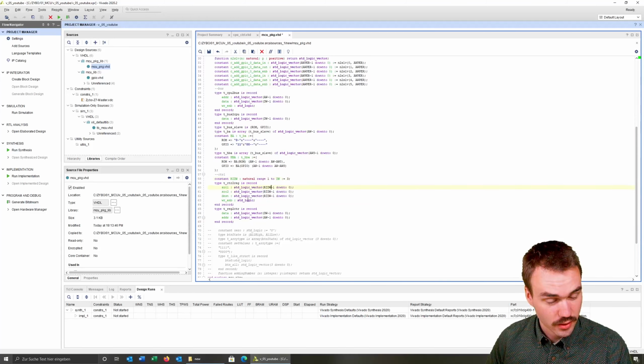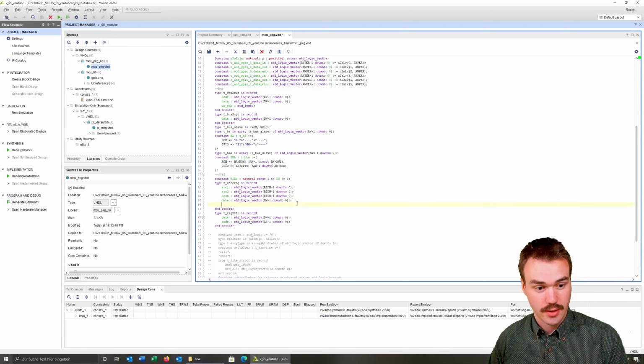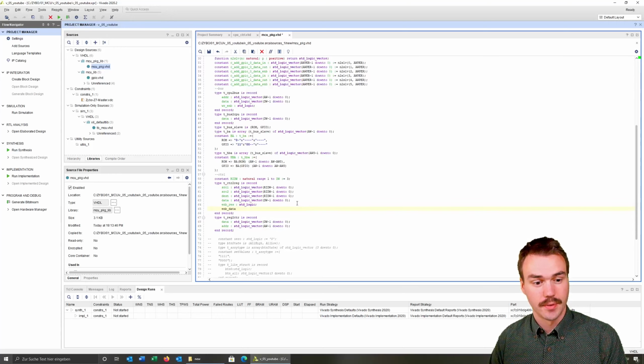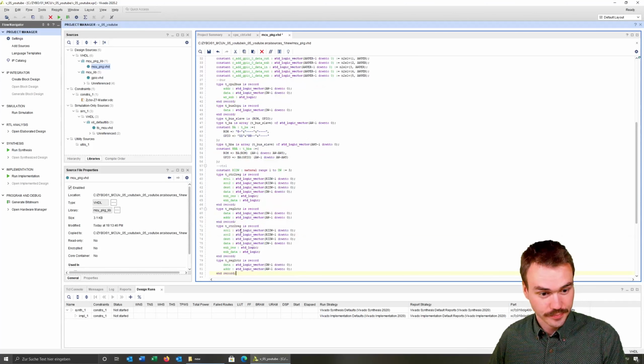And we see here all the errors are gone, but here we have some more signals like the data, which we can actually copy from there. And then the enable result, which is of the type STD logic, and the enable data, which is also of the type STD logic. Then we have the same for the program counter. So let's copy that.